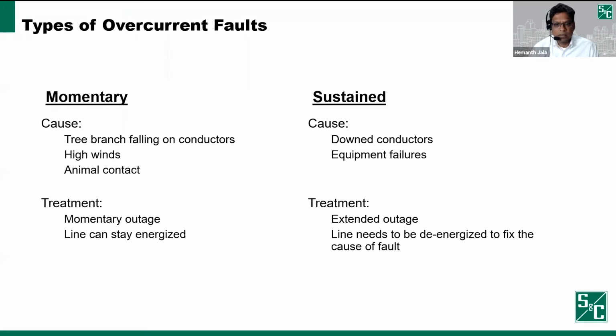Momentary is something where you have a fault that's temporary: a tree branch falls, conductors come in contact, and then the fault goes away. Or it could be Mr. Squirrel coming in contact with two conductors, and after that happens and there's no more fault, you're back in business.